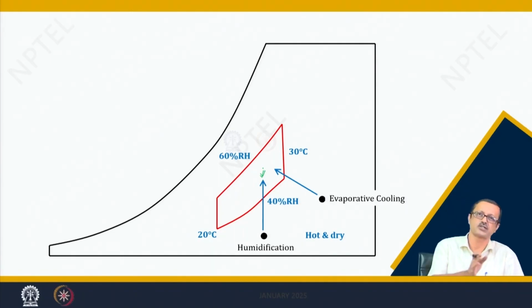So, again that has to be pushed up and placed within that particular red boundary zone, and it will not be a vertical push, it will be a slanting push towards up. That means you require some kind of cooling, and also some kind of evaporative cooling, because it is going towards the same WBT line, or parallel to the WBT line.